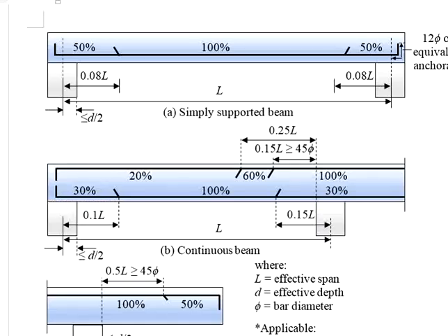Giving you an example. Let's say now you have calculated the amount of reinforcement bar required at the internal support here is 2T12. Based on the curtailment rules as illustrated here, you may reduce 40% of the amount of reinforcement bar up to a distance of 0.25 effective length, and then you may reduce further until 20% remaining towards the end support.